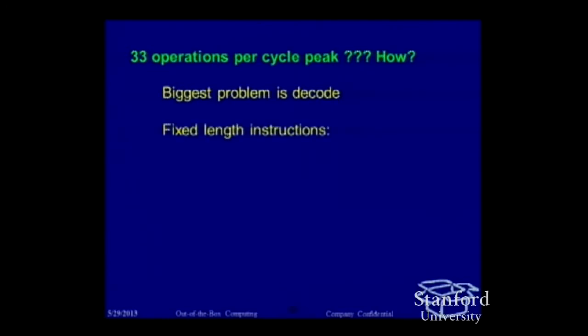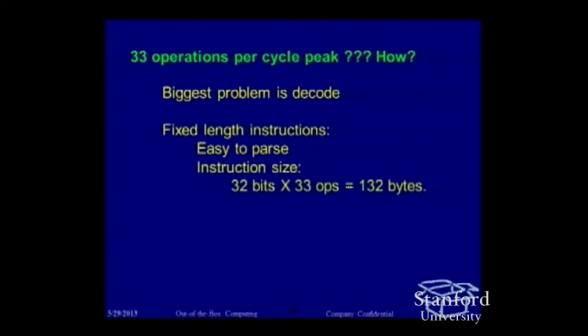There's two basic models for instruction layout. You can have fixed format instructions, where every instruction is the same length, your typical RISC instruction set. They are dirt easy to parse. You just drop the thing into a decoder, and the next one into a decoder, and the next thing in the decoder, and away you go. Bob's your uncle.